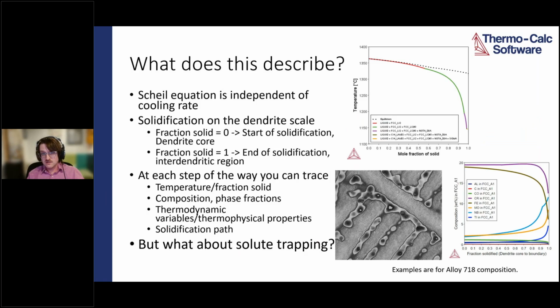And so this actually gives us a wealth of information related to the solidification and very much the non-equilibrium solidification behavior, how the alloy will actually solidify in real life under those assumptions, right? No diffusion in the solid and infinite diffusion in the liquid. And those assumptions don't always hold up, right? If we cooled very slowly, we might have some diffusion in the solid, but there are some equations and ways that you can handle that. And if we solidify very rapidly, that might also change things, right? And that actually is called solute trapping, we'll talk about.